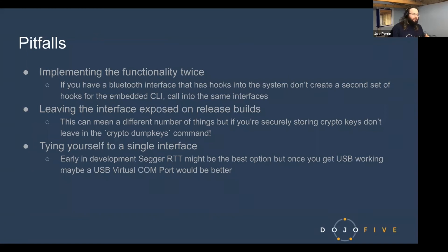So pitfalls. Right. So I had a customer, they had a CLI, they had Bluetooth, they both kind of implemented their own hooks, and they behaved slightly differently. And so basically they did the work twice because they were happening in parallel. But if you do this once, then you don't double that effort, and they'll behave the same. They ran into the problem like, oh, manufacturing wants to do this feature that's available over Bluetooth, but on the factory line, Bluetooth is not reliable enough because we have hundreds of these devices blasting in the Bluetooth spectrum. So we're just going to plug the UART in because the plastics aren't on the device yet. Well, it turned out that the UART interface was different and implemented differently.